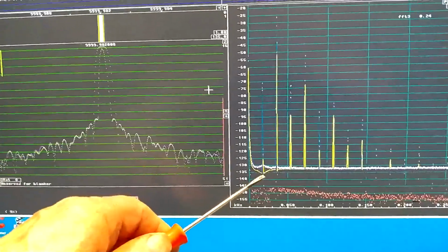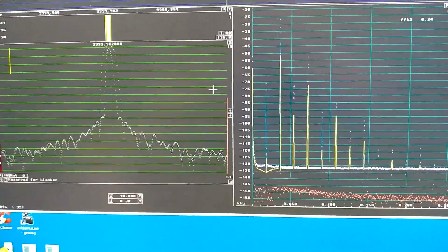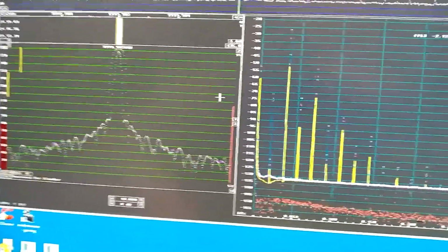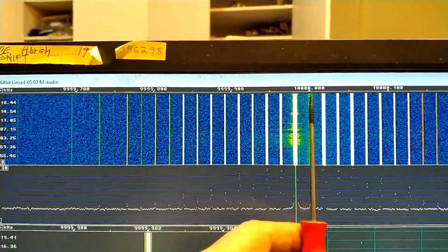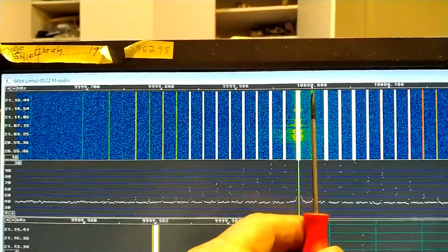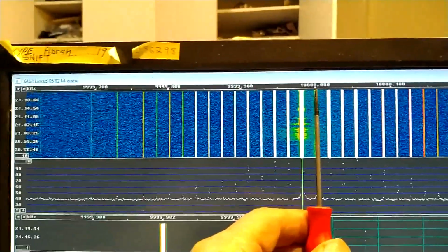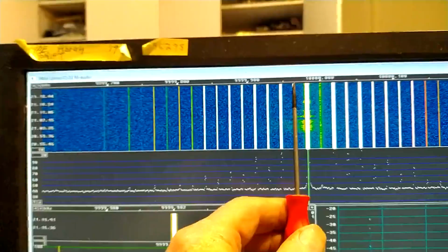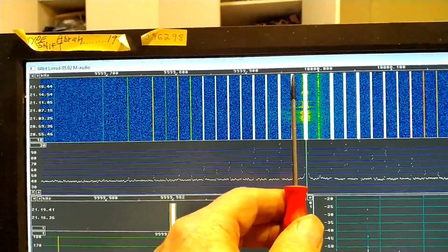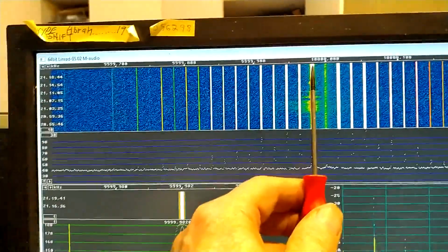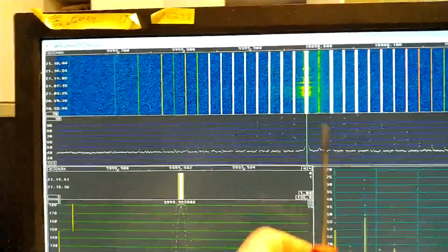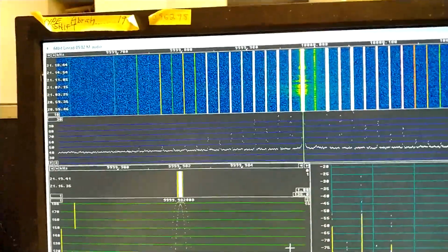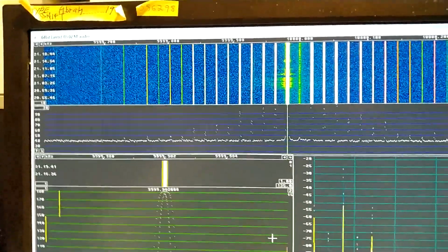So what happens here is a negative contribution in the real part. And it's caused by the zero frequency, DC, in the sound card. It gives 1 over F noise here. And together with the second harmonic, which is here, the audio side second harmonic. This is the signal, second, third, and so forth. So these two together give a contribution with the negative side.